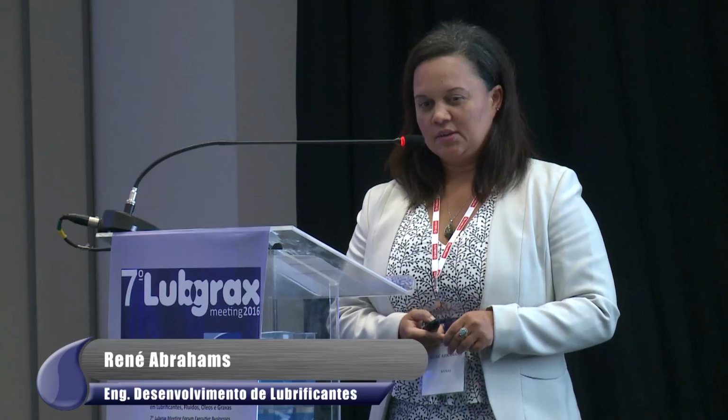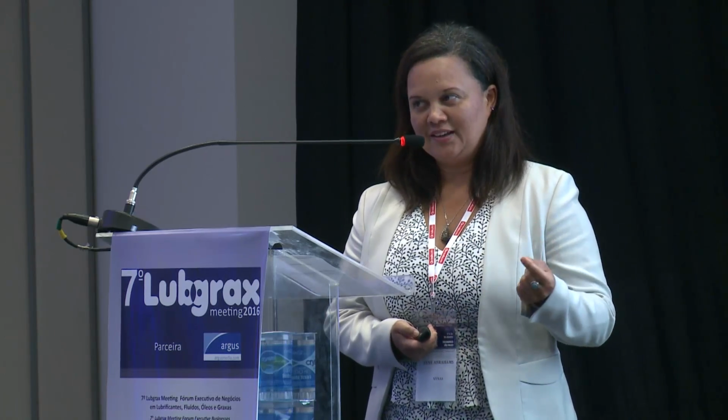So grease A is the group 1, and grease B and C are the new NYNAS-based products. What's interesting to note is that there's very little difference in the pour points of the oil. But as a grease, there's a significant difference in the performance at extremely low temperatures. This is important for sort of Nordic or Arctic conditions. Here, it's probably the wax crystallization starting at a much earlier stage than perhaps anticipated, or perhaps earlier than the pour point would indicate.